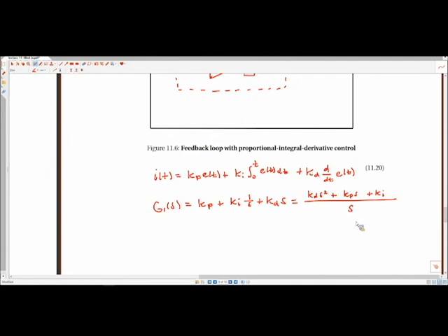Okay. My question, I guess, on that is, it almost seems like from these notes that you want your integral term to be really low, just because we're only using that to get to the steady state value, while our derivative term is more damping on our system. So it almost seems like you want a higher derivative term and a medium or lower integral term.